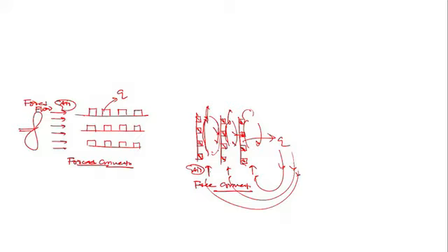and the rise in temperature causes a decrease in density, and that density difference causes the flow, because ambient air is of heavier density, while the air near the surface of the components is at higher temperature, that's why lower density. That density difference causes a force to be induced, that is the buoyancy force, and that causes the naturally driven flow. This is pure convection, free convection. Yes or no?